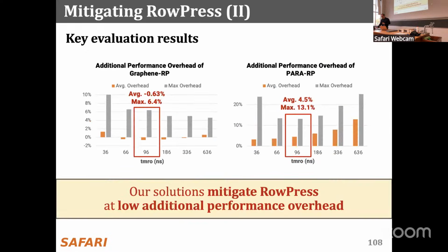Okay, so you can see the mitigations, but PARA's performance overhead increases significantly, as you can see. So there's low additional performance overhead on average, but it's still not comfortable, basically. Meaning, as you keep finding these disturbance mechanisms or bit flip mechanisms, you're going to be less and less comfortable because your performance overhead to mitigate them will increase and increase.